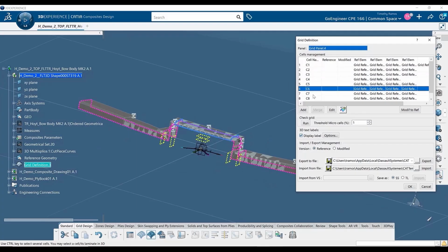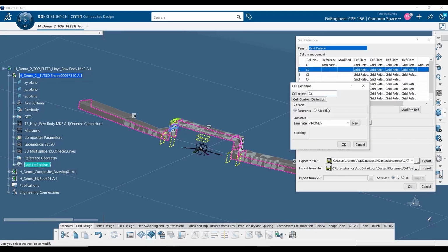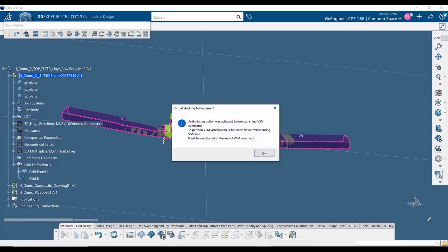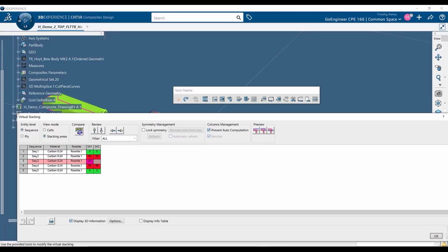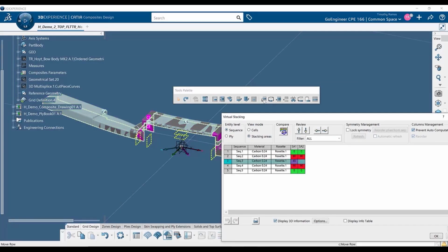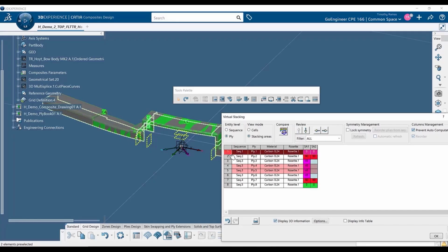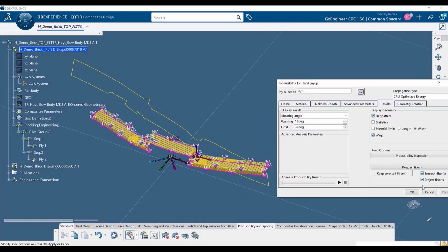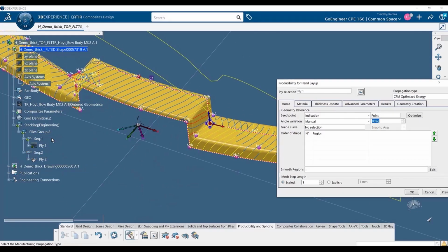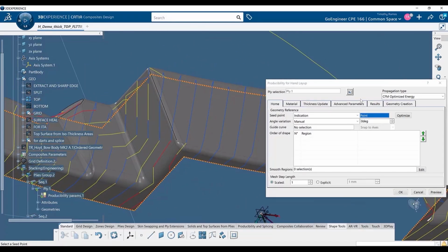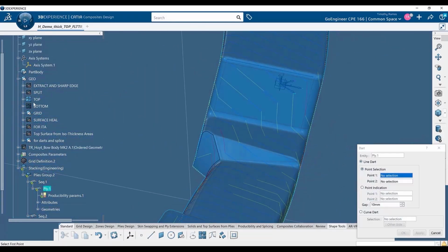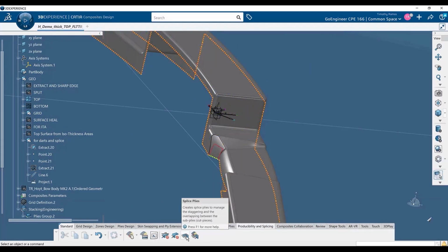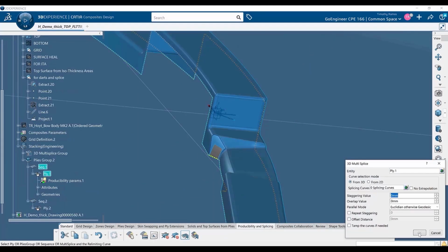Within these tools, you can design and define your entire ply stacking, build your top surfaces and resulting solids, as well as generate your flat patterns while considering the thickness changes as more and more plies are laid. On top of generating plies, you can also run simulations for producibility, which checks the warp and weft of the plies during the hand layup process. Simultaneously, you can also check the ply size against the roll width, as well as apply darts and splices where necessary.